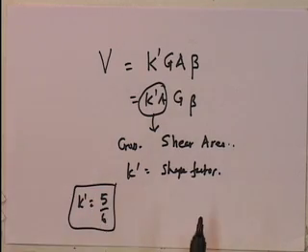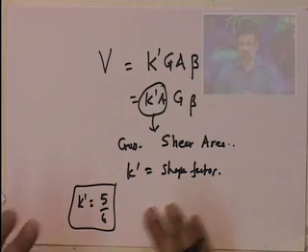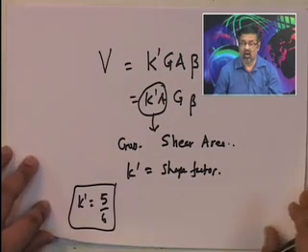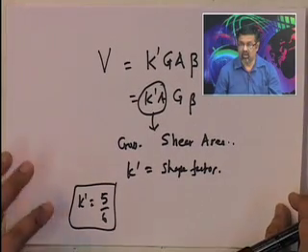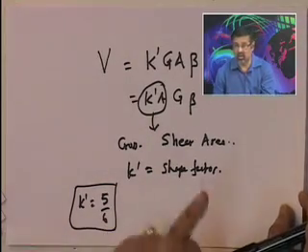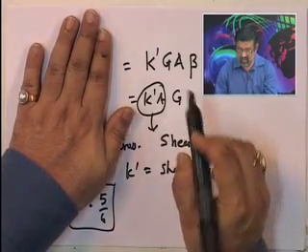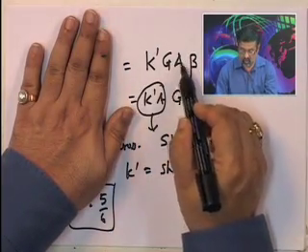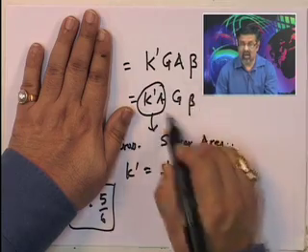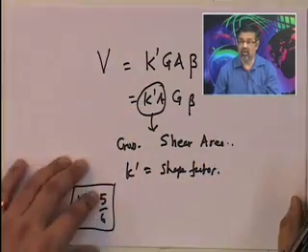This is something that we know already from structural analysis. So, I am just rewriting it. So, V is equal to K bar G A beta, where beta is the shear distortion. So, in a way what we are writing is shear force is equal to area into G, G into A is like a force into the distortion, angular distortion.